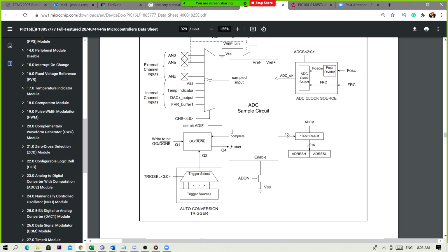All right. And on the right-hand side, just where you're looking there now, all of this circuitry has to do with when you start sampling and when you finish sampling. Because remember when we talked about that sample and hold, right? So you have to have a sequence. It has to catch the voltage, disconnect, and hold the voltage while we're converting. When it's finished converting, it needs to reconnect, catch a new voltage, disconnect, and convert that voltage. That's how it's going to work in sequence. Make sense? All right. Now you asked a good question about where the inputs come from.